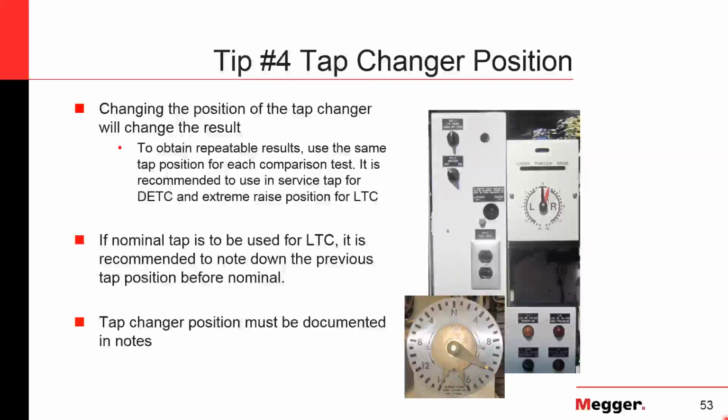And if you are going from the secondary, and if I understand this correctly, it's going to be your low voltage side, right? The 10 volts or 20 volts that people will be applying for this test may go a little bit beyond the limits that you may have for your high voltage side current. So it's safer and it's better just to run it from the high voltage side.